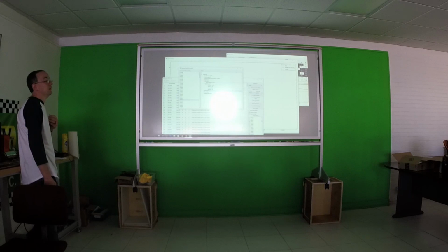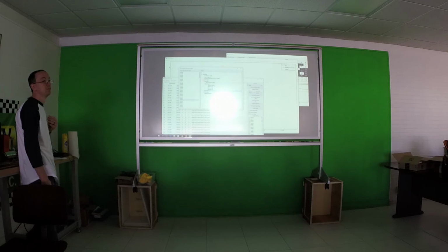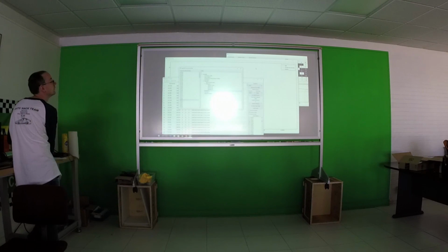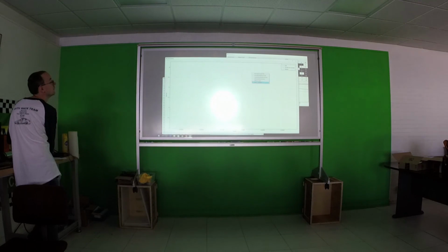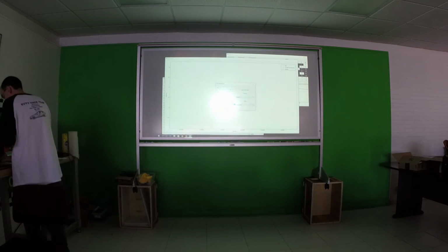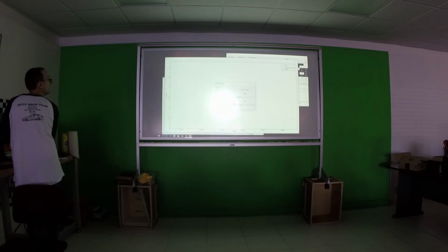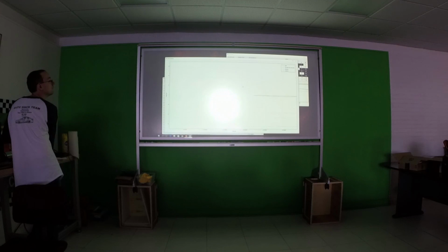But in the case of the Tesla, bizarrely, you change this value and you have to send about 9 frames minimum, 9 to 18 frames. And then you go back to normal operation, and the inverter picks this up and recognizes it as valid because of that clock and the security byte at the end. So it only flashes up there for 8 or 9 frames, and this is, I think, a 100 millisecond, or maybe a 20 millisecond frame rate. And then it goes away. So you don't have a state machine, it's just a signal that the inverter has to catch.